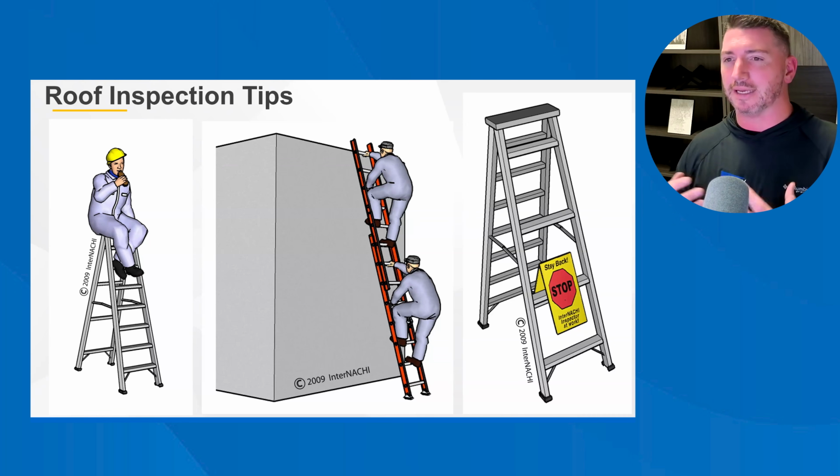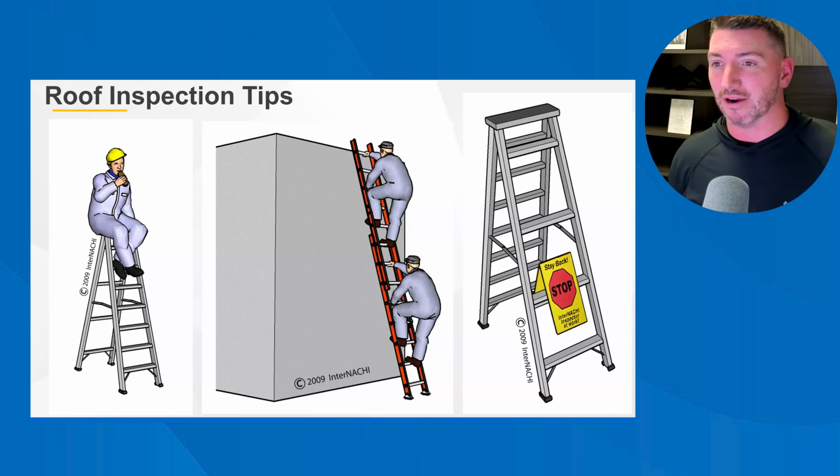It's once you start adding in different facing slopes that meet in valleys, you have a lot of appurtenances. People want solar panels, and I've seen the solar water heaters and skylights. Skylights are usually a nightmare. So those are the areas that you really want to hone in on and see, do I see any serious workmanship issues in these areas? Do I see anything breaking down, deteriorating?